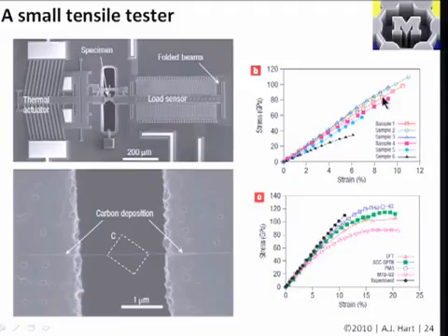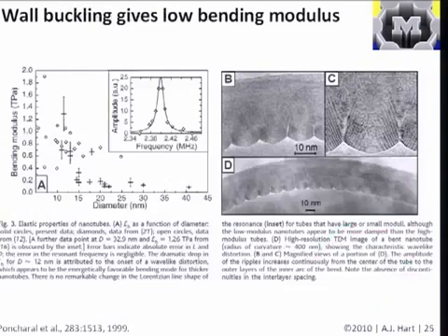And this distribution gets to the statistical aspect of failure at the nanoscale. Failure is statistical at any scale, and if you have 10 bars of brass, they're not all going to fail at the same stress. But it becomes even more important when you get down to a small volume, where the number of defects may be greatly different because you have such a small chance for only a few defects to accumulate. There are also some other interesting things about.